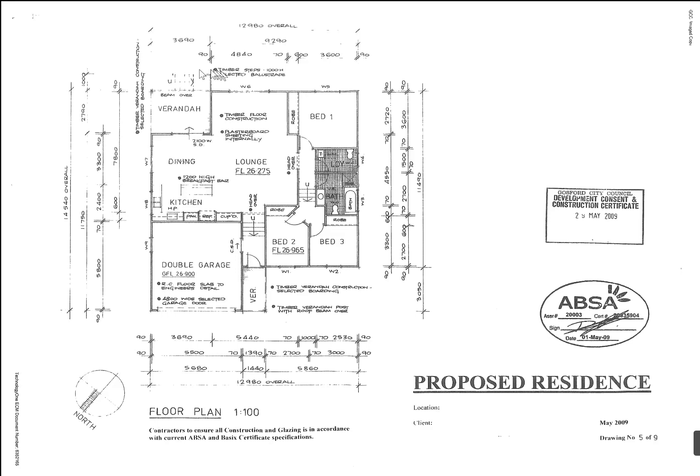Okay, we're going to come down. So basically you can pick off the overall dimensions, and as you move closer to the building you're getting more and more detail. These little horizontal lines that come out from the building are what we call witness lines, and the diagonal slashes indicate the extent of the measurement. So this 600 here relates to that internal measurement there.